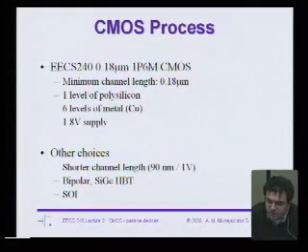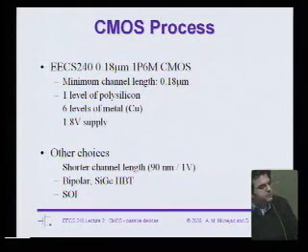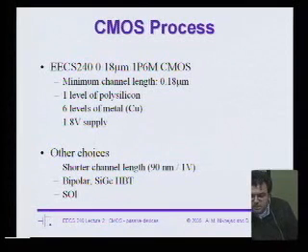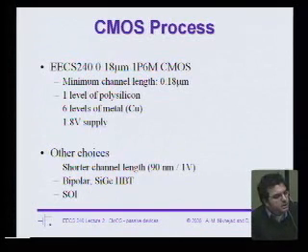So why 0.18? Why not just go into a 90 nanometer process, which is available commercially today, or even a 65 nanometer process? And for that matter, why not bipolar or silicon germanium, or SOI or FinFETs? There's a good balance between something that's realistic and useful, and something that would just be a pain in the butt. If we use a 90 nanometer process, you'd have to deal with all sorts of issues like leakage. That would be good for a pure design course, let's say a 290 course, but probably not appropriate in this class. Some of the students in 142 can attest to this: using a new process technology, a transistor doesn't look much like a transistor, and so you spend a lot of time wrestling with the transistor rather than actually doing good design.